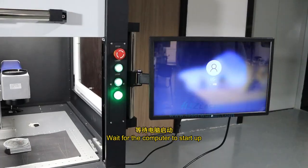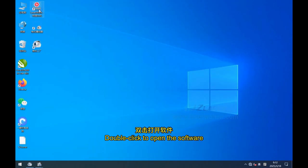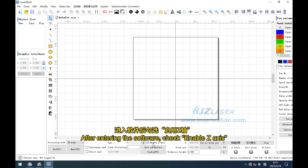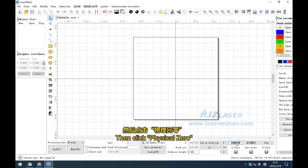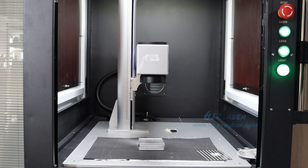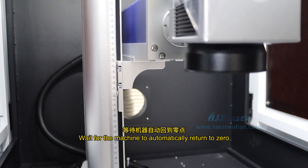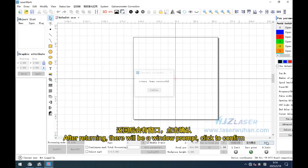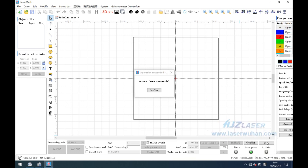Waiting for the computer to start up, double-click to open the software. After entering the software, check Enable Z-axis. Then click Physical 0. Wait for the machine to automatically return to 0. After returning, there will be a window prompt. Click to confirm.